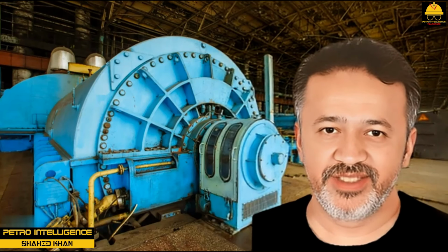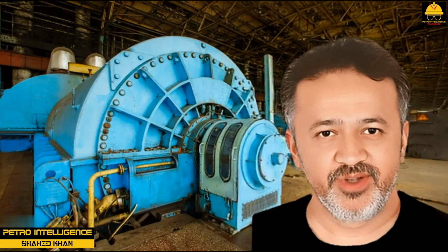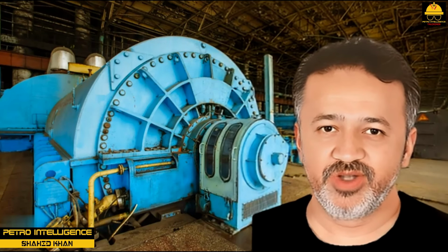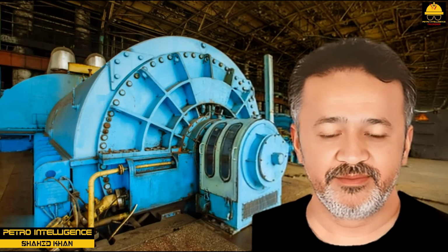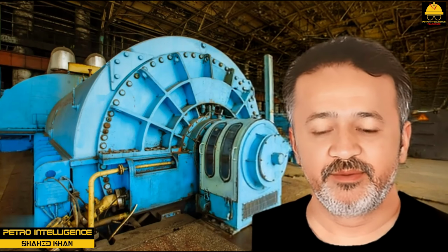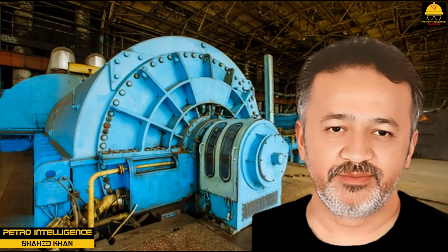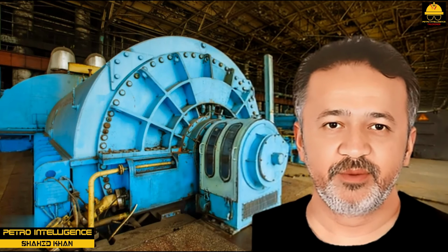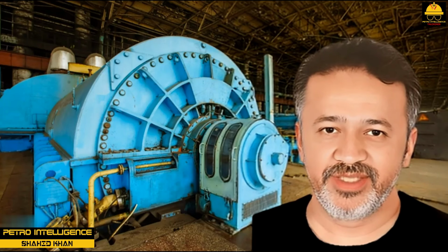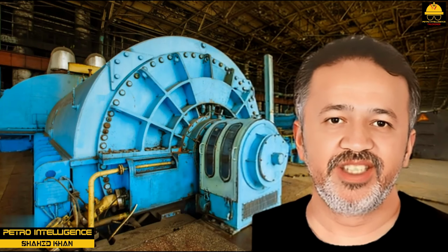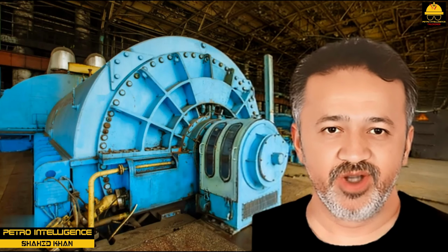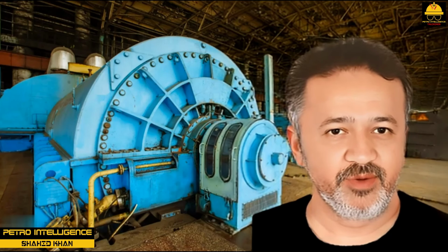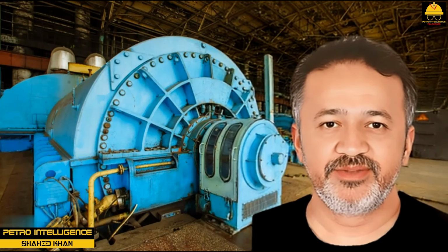The chemical processing industry attempts to maintain constant pressures on utility steam heads. Occasionally, boilers go down, or larger demands are made on the system. A fluctuation in the suction steam pressure affects the turbine. On hot days, the system may work perfectly, but cold weather might create problems for your turbine. Some steam turbines are equipped with hand valves that can be opened to admit more steam into the system or closed to reduce flow. Hand valves typically are opened during high-load operation and closed during low-load operation.